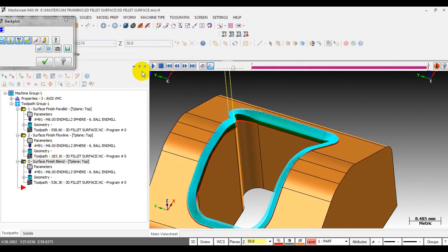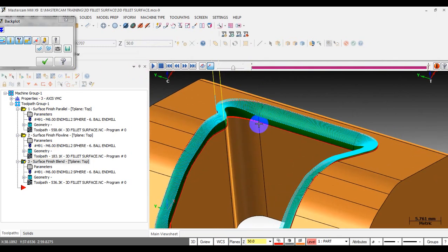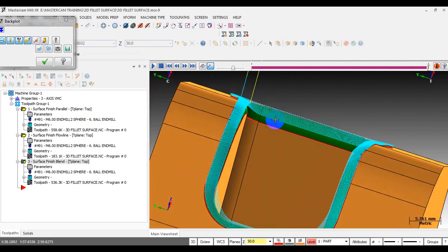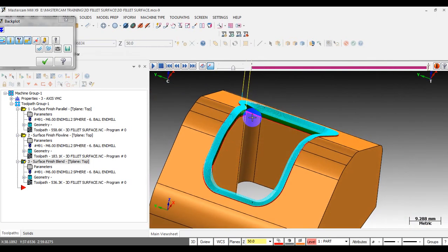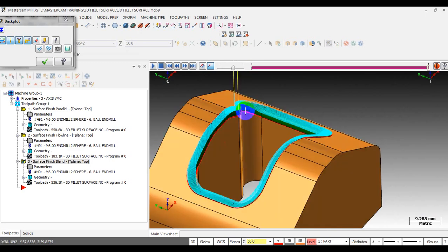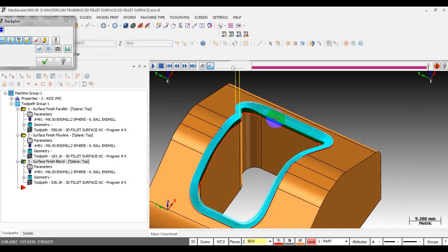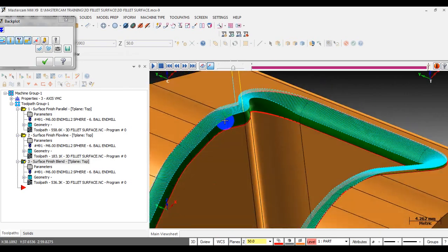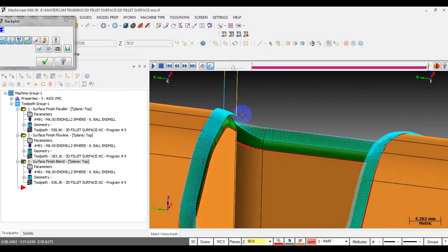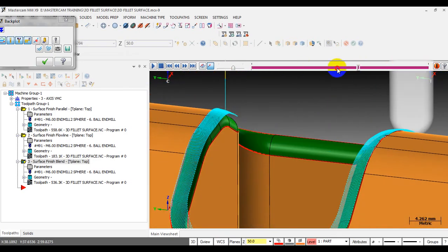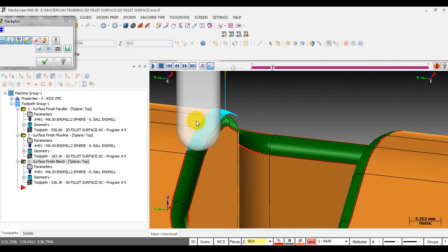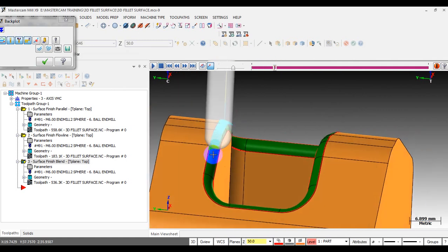But one thing I told you, you can see that for plane toolpath, the tool center will stay within the curve. Yes, the curve we define. So you can see here, the tool cannot make a finished cut, because the tool center will stay within the curve we selected.